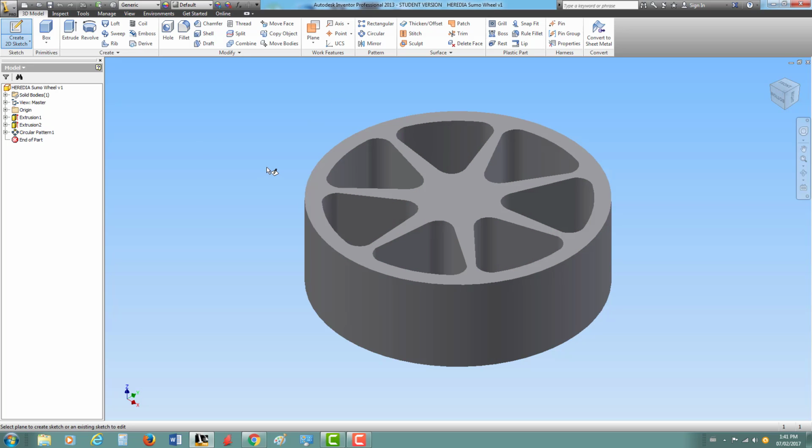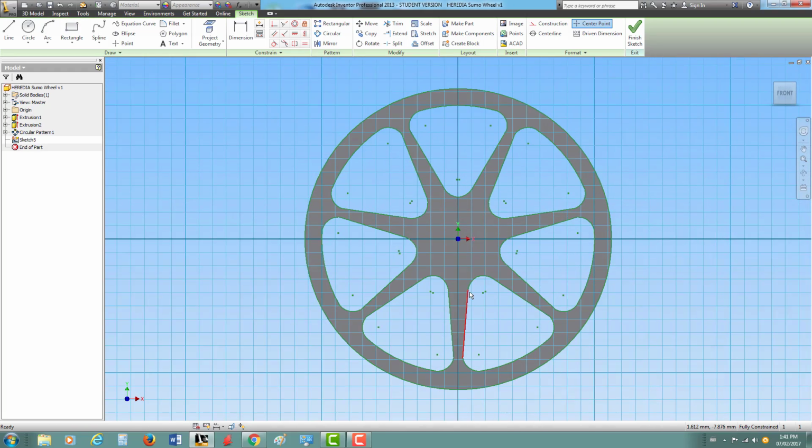So as always, we want to start a new sketch, and I'm going to draw the shape of the hole on top over here, because I'm going to make the hole directly through the center right here. Okay, great, I've got my sketch started. Now, one thing that might happen is if you are using Inventor 2013, I think 1 or 2 computers still have it, there's a function called auto project edges that's selected. It can be great in some situations, but in this situation it's going to be my major pain.